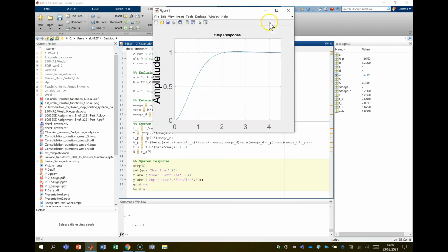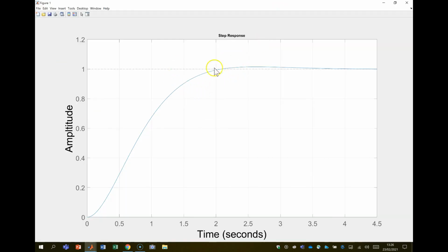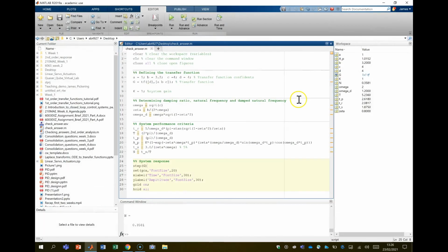So one final thing you can do is click this section and run your system response, so you know, your hand-drawn sketch at the end. You could then put a step input into the system, and you can click on the response and drag this to get amplitude and time values. So you can see how this relates to the hand calculations you've determined and the various properties.